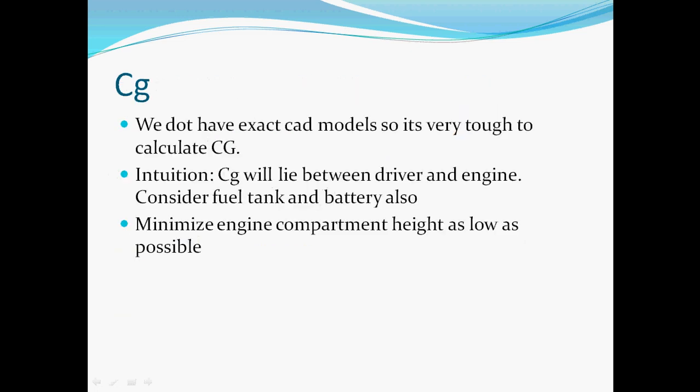See, we do not have an exact model, so it's very tough to calculate CG. So what I did, I assumed CG between driver and engine, because they are the most heavy part of the vehicle. So between the driver and engine, I assumed one CG and then I continued with it. If you have one previous car, then you can probably calculate CG. But if you are designing it first time, then calculation of CG is very tough.